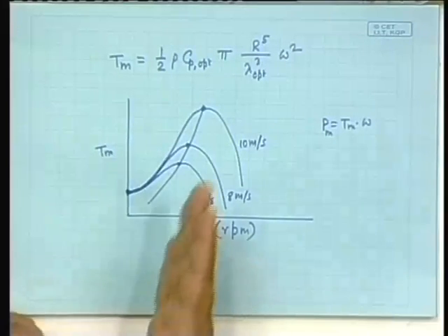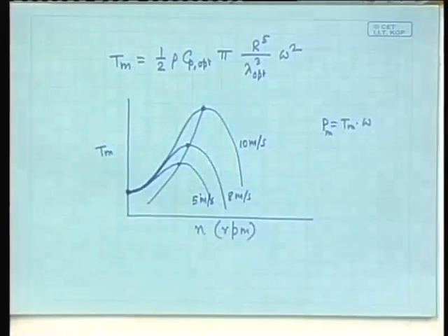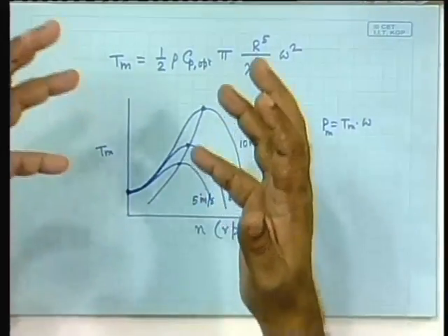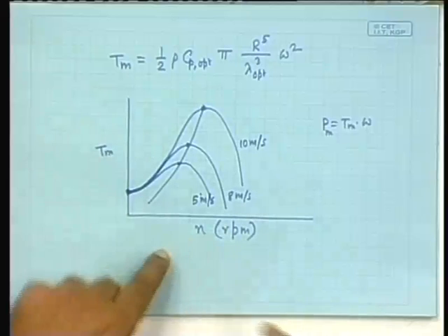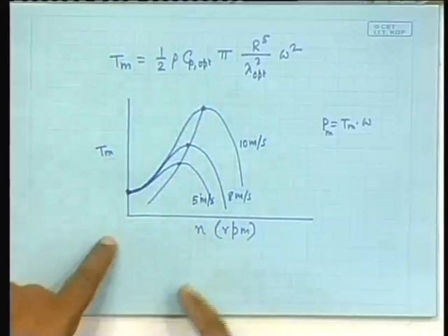Similarly, when you are using it as an electrical source, that means it is being converted to electrical energy and that is supplying some kind of a load, then it will also have its own torque versus speed characteristics. Nowadays all these mostly are not directly connected, rather they go through some kind of a power electronic interface through which it is possible to control the power and hence the torque. If you do so, you might argue that then it is possible to have exactly the load torque also proportional to the square of the speed.